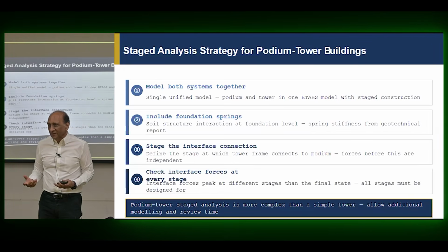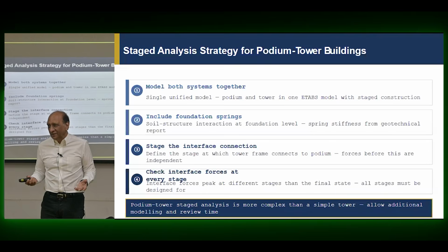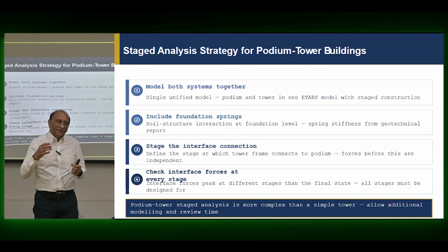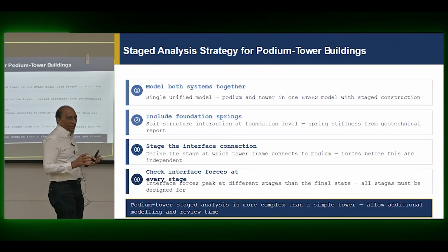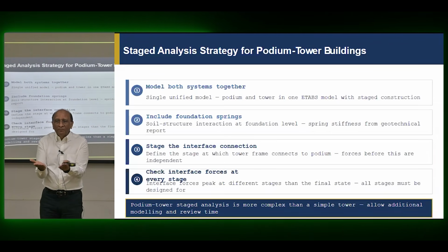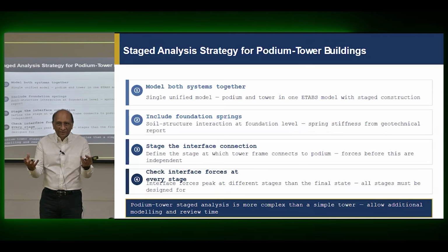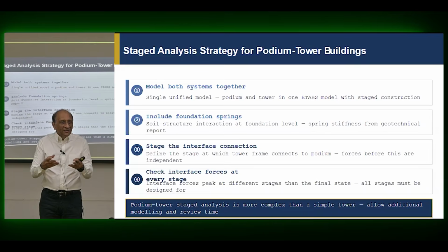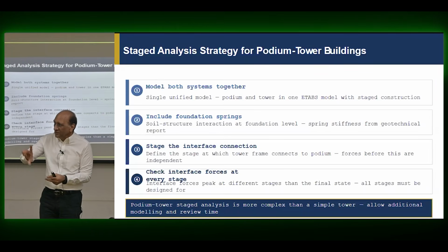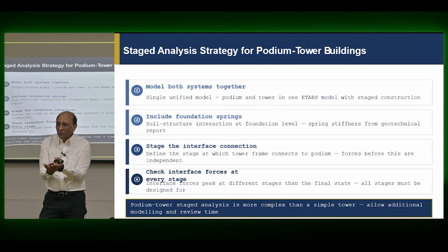What is the problem that I'm trying to solve? What are the issues? What is the thing that I should remember? That's the way to think about the problem, right? Because if you don't, then you will not understand whether ETABS did it correctly or not. So the right way of thinking is, like you said, take each tower and model it above the podium, assuming that at the podium level they are on a big foundation, so they are kind of fixed at the podium level. So take each tower separately and stop it at the top of the podium.